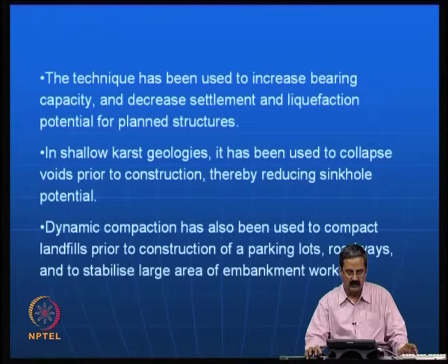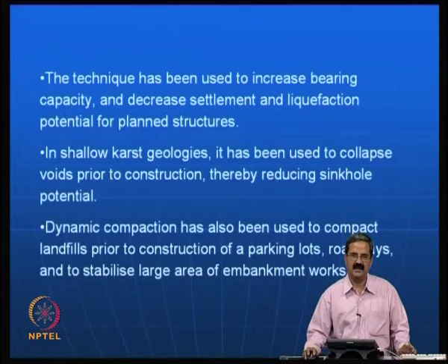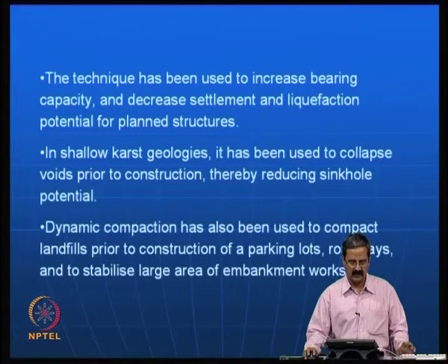We have also been using dynamic compaction for many landfill projects, because the problem with landfills is that they have a heterogeneous mixture of waste like paper, food, construction debris and other waste materials. It is very difficult to compact waste materials in a systematic way, but dynamic compaction has been quite useful.